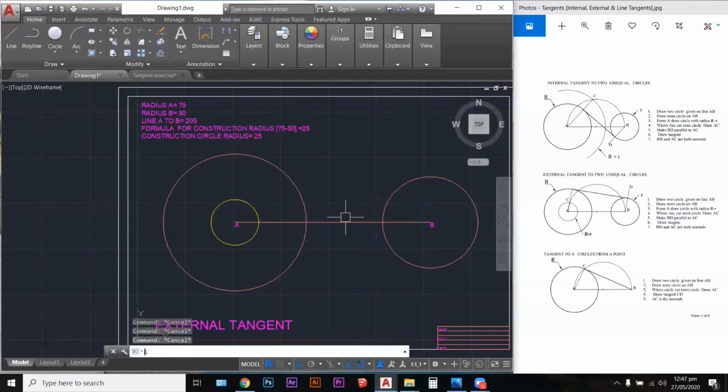I'm going to hit L for line, and I'm just going to hover over where I think my midpoint is, just to show you that's the symbol for midpoint, which is a triangle, and then it comes up midpoint. I think it's fairly good, because if you can't remember what the symbols mean, you're also given the term, the meaning.